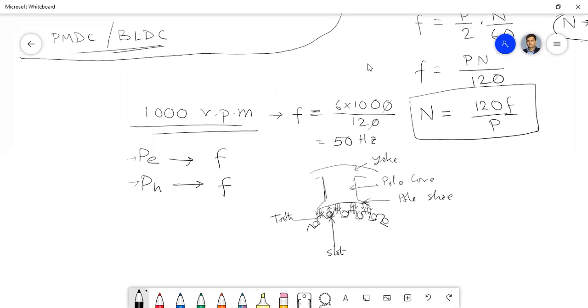Okay, so conductors pass through the slot, and the extended portion of the armature pole is called the tooth. Okay, and this tooth plus slot is called one slot pitch. So flux generally flows through the tooth because it gets a minimum reluctance path through it.